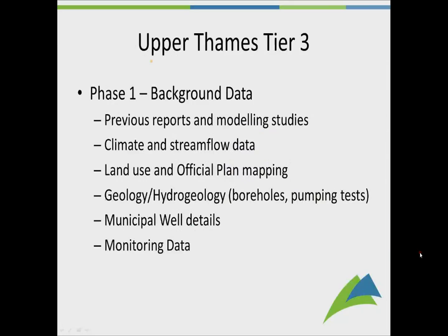So as with many model projects, there's a phased approach to building the models. The first phase being assembling and gathering all the background data, including previous consulting reports, government reports, any climate data such as precipitation, streamflow data, land use maps, as well as official planning maps from the municipal governments, borehole logs, pumping tests, and any other geologic or hydrogeologic data, municipal well pumping data from the municipalities as well, and any other monitoring data to get transient water levels over time.